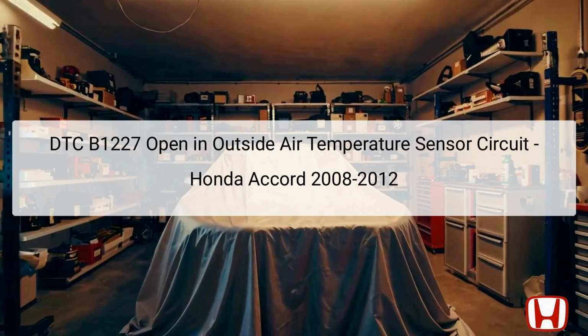The Diagnostic Trouble Code DTC B1227 indicates an open circuit in the outside air temperature sensor on a Honda Accord manufactured between 2008 and 2012. This issue can impair the vehicle's climate control system, affecting the accuracy of outside temperature readings. The outside air temperature sensor plays a crucial role by providing ambient temperature data to the climate control unit, which adjusts the heating and cooling systems accordingly.